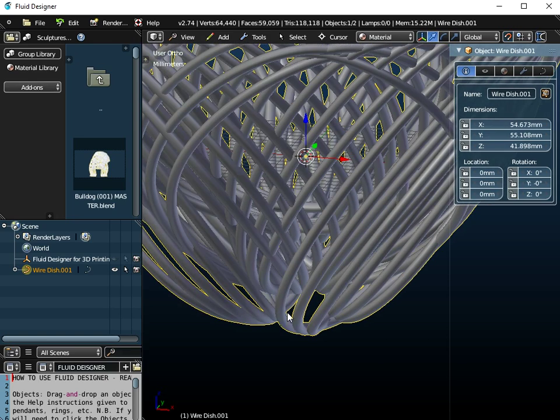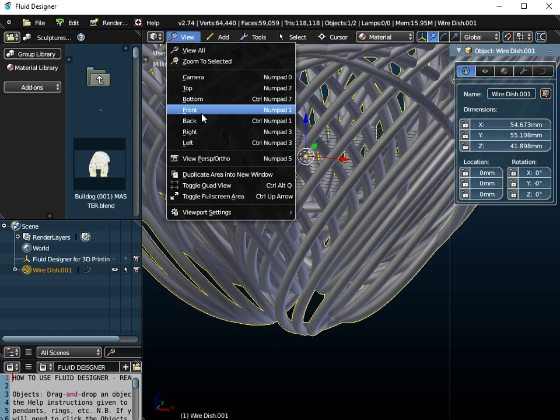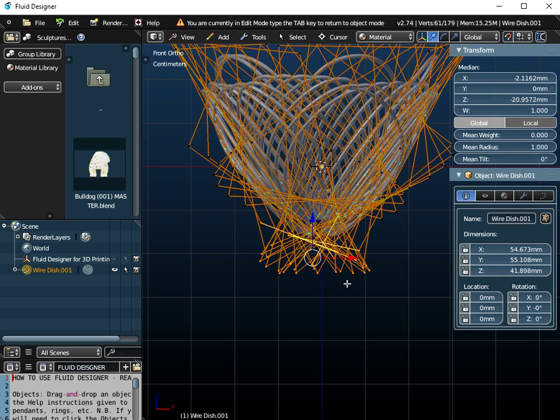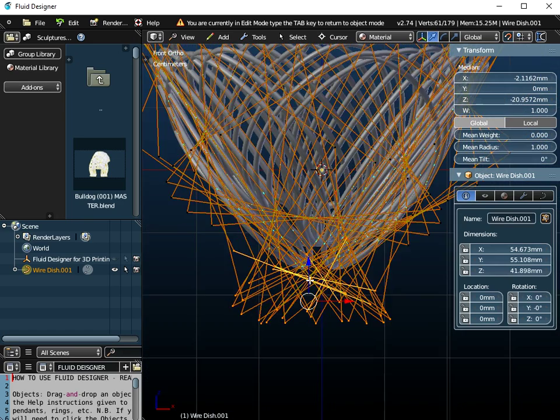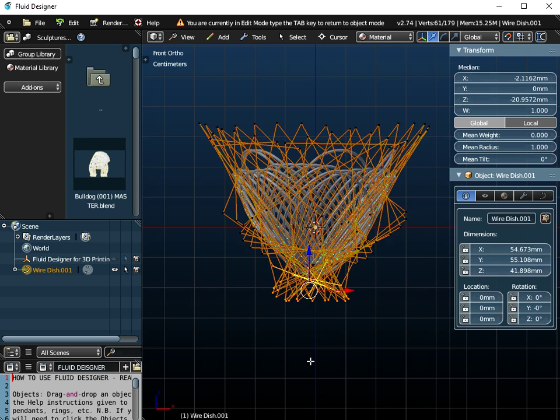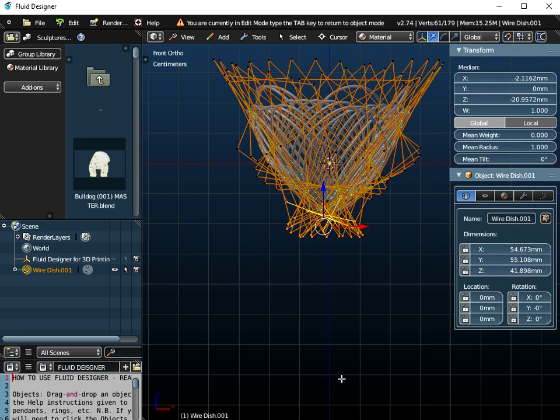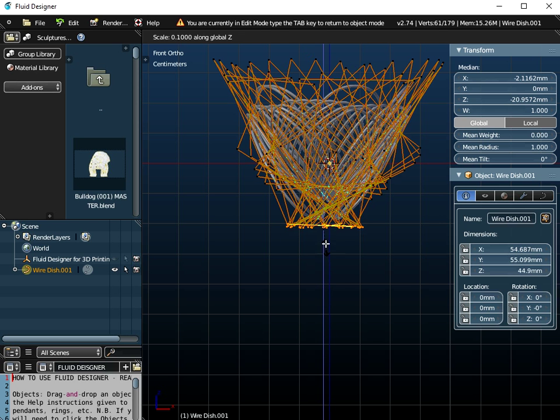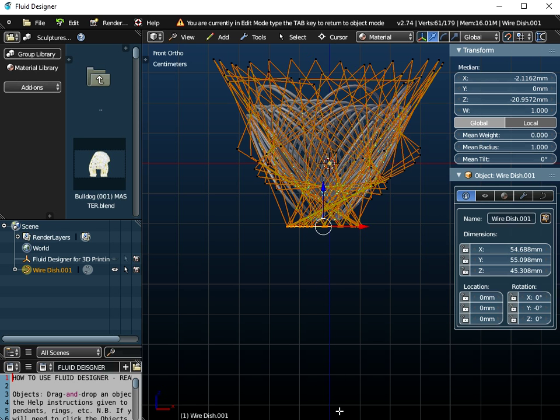What I could also do is flatten off the bottom of this. So if I go into edit mode now, if I keep those highlighted, the blue arrow is the Z direction. If I press S on the keyboard to scale and restrict my scaling to the Z direction only, so I've pressed Z on the keyboard, I can bring those control points and straighten them up.